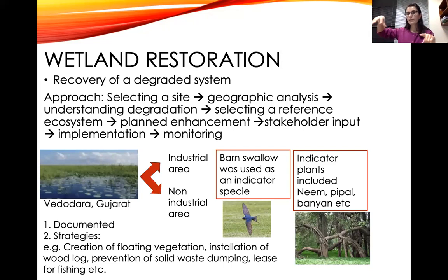So let's say we have installed a well here and we are drinking water here, and a pollutant was thrown away from it. Because we're extracting water, that pollutant would come towards the drinking water source, which is why your drinking water sources should also be monitored. Because if they're close to industrial sites, that means that you're prone to these chemicals as well. So it's quite complicated, Taha. But generally, these soil remediation techniques are coupled with groundwater remediation techniques as well. So yeah, that's as simply as I can put it.